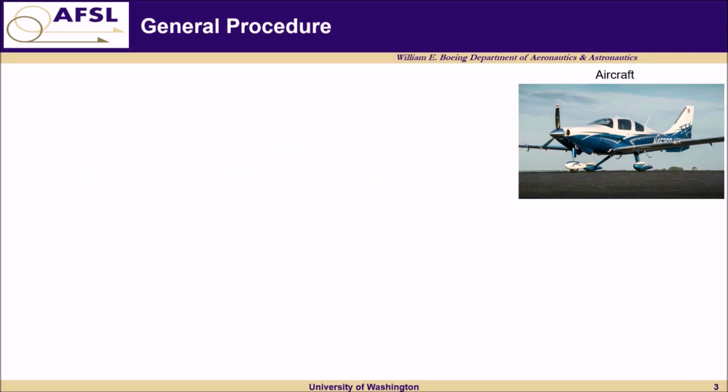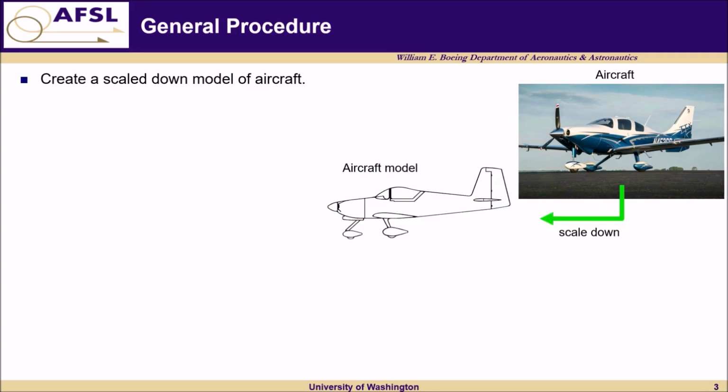So that was what we want to do. How are we going to do this? So again, at a high level, conducting a wind tunnel test is actually fairly straightforward. So let's start with the aircraft. Now, as you can imagine, a full-scale aircraft is too big to fit in most wind tunnels, so we're going to need to create a scaled-down aircraft model.